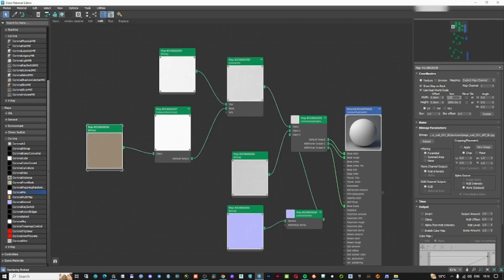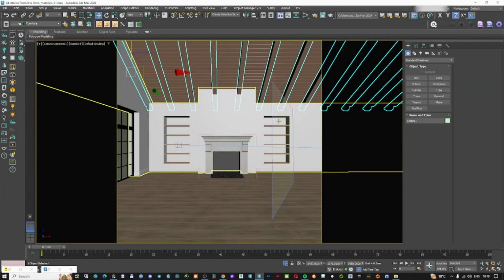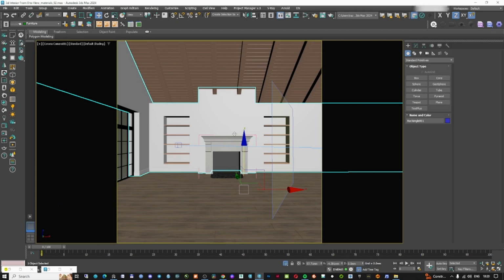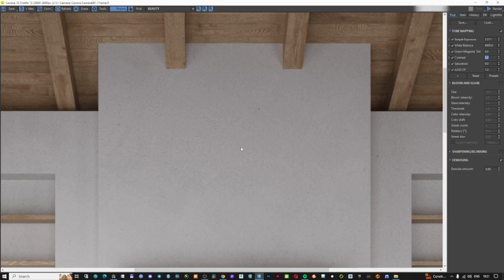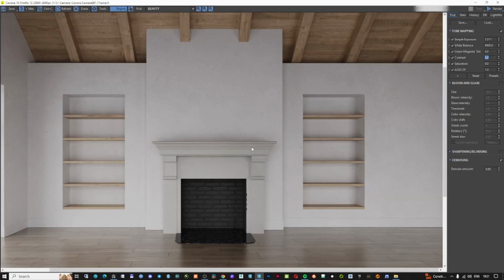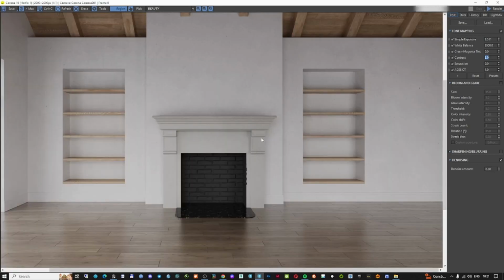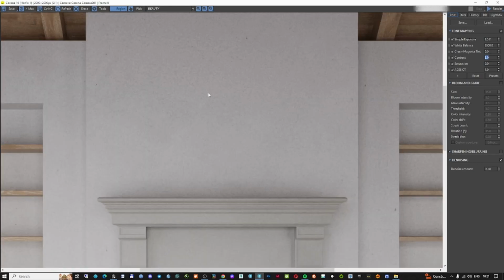It's also 1000 by 1000. So here. So yeah, it should be fine now. Okay, I'll just save my file. So yeah, one thing that is very important when you create renders is to have the textures on the right scale. Most of the time, all these websites are not providing you the right scale for the textures. So sometimes, yeah, you just need to think about it, how big this texture is going to be. While making a couple of tests, you can actually see it.